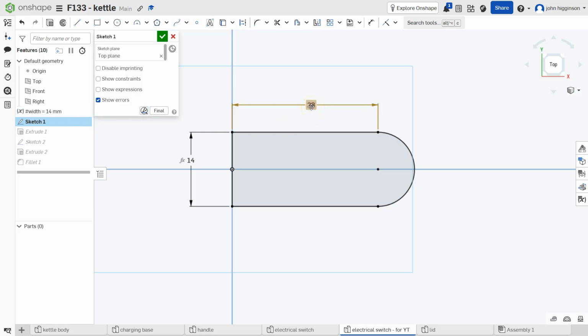Also, we can do formulas or calculations with that variable. I want this to be 28, which is 2 times the width. So what I can do here is type hashtag width, and I want that multiplied by 2. That's shift 8, the asterisk rather than the X, and then hopefully that will be 28.